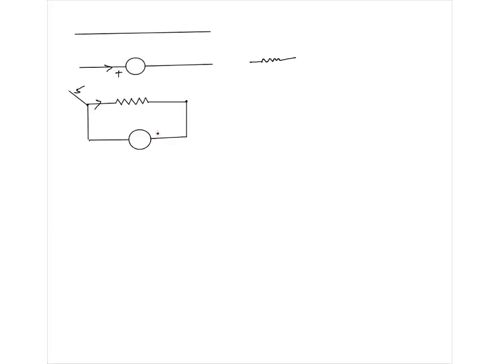That is fitted in some factory, the coil, etc. So you don't fiddle with the coil, but you can connect a resistor in series. Supposing you have a factory-made galvanometer with the coil fitted, but you are seeing the 2 points and you connect a resistor of your choice here.